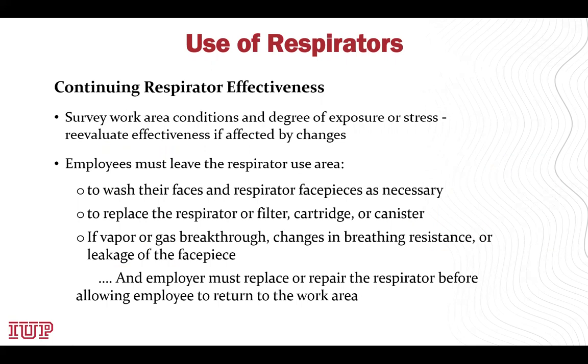Continuing respirator effectiveness. We want to maintain appropriate surveillance of the work area conditions and degree of exposure or stress. Reevaluate the respirator's effectiveness when it may be affected by changes in the workplace. Employees must leave the respirator use area to wash their faces and respirator facepiece as necessary, to replace the respirator or filter, cartridge or canister. If the employee detects vapor or gas breakthrough, changes in breathing resistance, or leakage of the facepiece, the employer must replace or repair the respirator before allowing the employee to return to the work area.